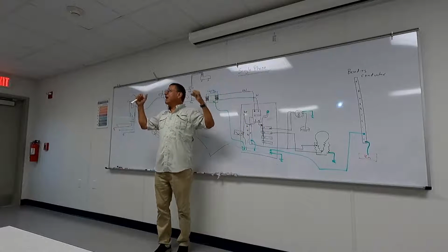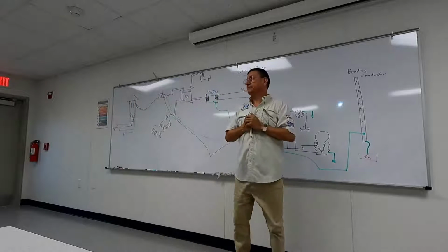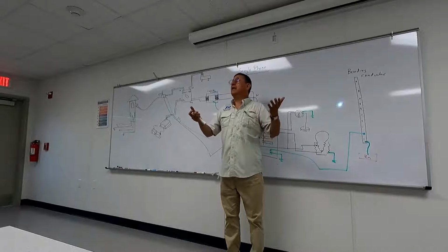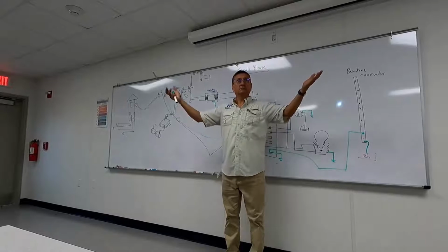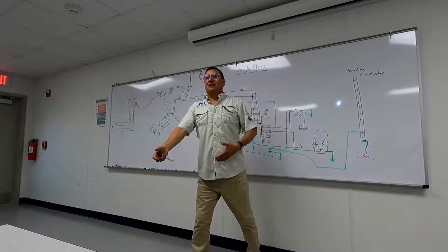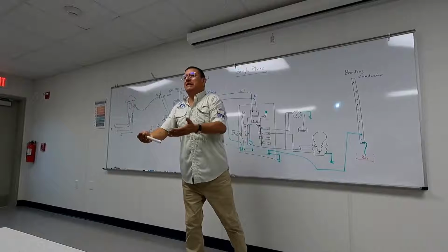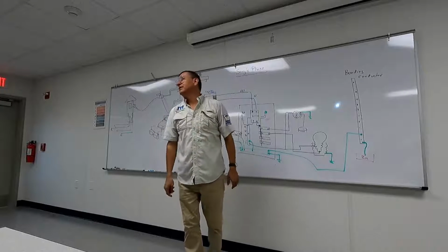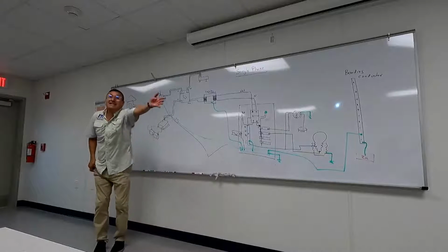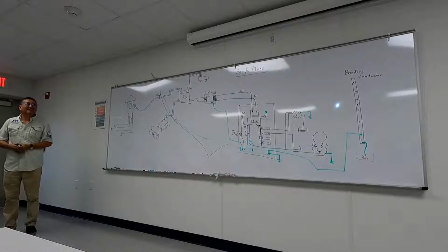Reverse polarity? Yeah. And why is reverse polarity catastrophic? You understand, guys? It's because the ground right now will be hot. And the ground is connected with the bonding. And I have a lot of metallic elements connected to the bonding. And those metallic elements right now receive 120. Wow. One thing you gotta think about: if you electrify, your gas tank is bonded with 120. You have 120 volts with a full 100-gallon fuel tank.